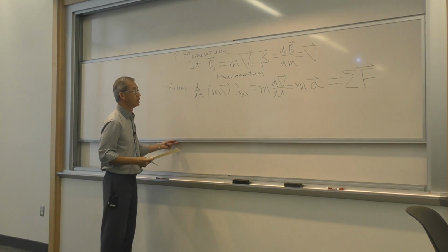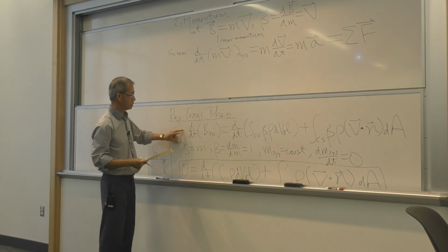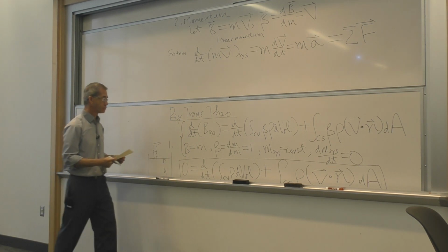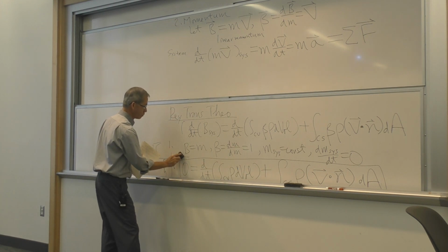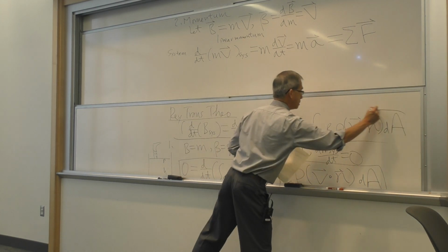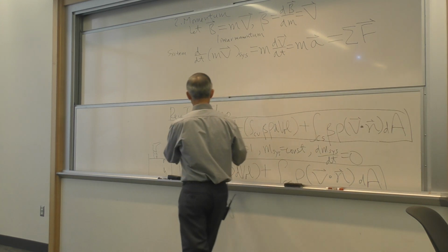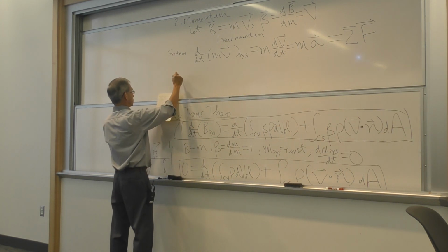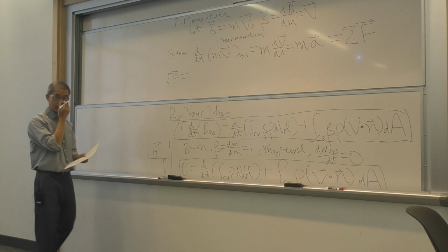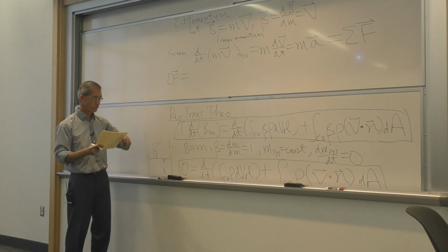So now I'm in a position to use the Reynolds transport theorem, which is stated in here. I'm just going to replace all those variables. Now apply to momentum in this equation and see what comes out. So in doing that, I have forces on the left. That's the rate of change of this term here for the system, which we are convinced is equal to the force.